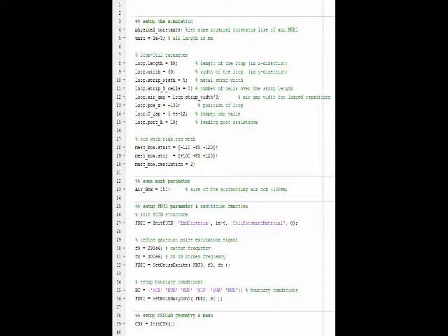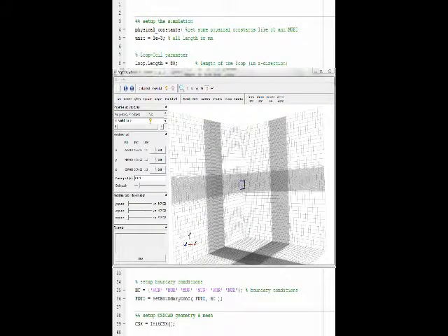We then create some mesh parameters, such as the air box. The air box has an edge of 150 millimeters. It is the size of the box that contains the loop. The loop we created is really small. It is 80 times 60, but the box is 150. That's the reason why we have a really small loop in this big air box, as showing in the picture above.